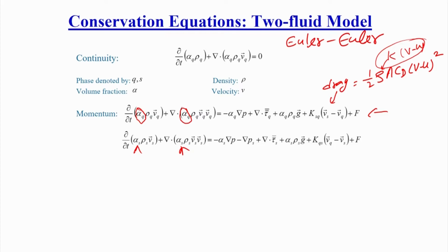Now, there is only one pressure term here. We include one more pressure, and that is the solid pressure term. We keep this term exactly the same, alpha s into delta p, but instead of the gas phase volume fraction, you now multiply with the solid phase volume fraction, and we subtract that solid pressure term. Why the solid pressure term has been included and how it is defined, we will discuss in the next slide. Then we use a solid stress term.